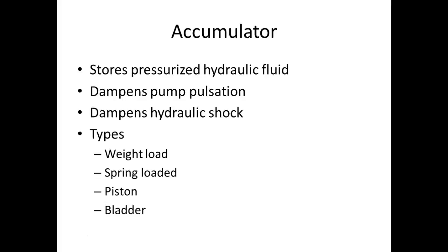So they had to come up with some method to maintain hydraulic pressure even though the pump wasn't spinning. They came up with something called an accumulator. An accumulator is just a big old tank. It's usually vertical. They either use big springs in there, and when the hydraulic pressure is going, the pressure pushes the spring up, and if the prime mover ever goes off, then it gets pressure from the spring. They use inflated bellows. They use big old weights. There are different ways they can set up an accumulator.